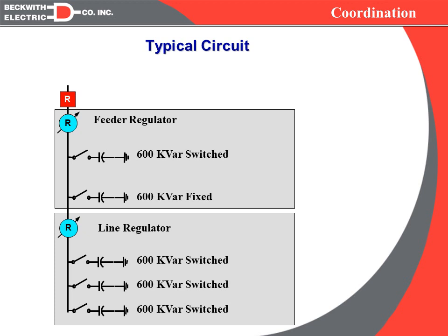Likewise, on this section of circuit, we need to coordinate. This is a fixed bank, so there's no coordination with it. We only have the one switch bank, so we would coordinate its time delay with this regulator. And again, we would coordinate with a negative X for the VAR flow. So that is typically how we would coordinate the settings on any given feeder.